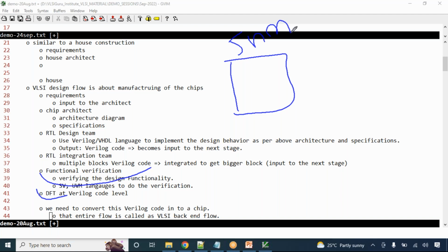That kind of transistor is a 5 nanometer transistor. Working at 5 nanometer, it is a very small number. You can imagine that also, right? You take a hair or a thread, you cut it vertically 1000 times or 100 times. What you get is a nanometer. That small it is. When you are manufacturing at that level, what is possible is that sometimes two metals can just touch each other. Any such kind of issues can happen. Some line gets always connected to the voltage line. Some wire will always get connected to the ground. They are all called manufacturing defects.